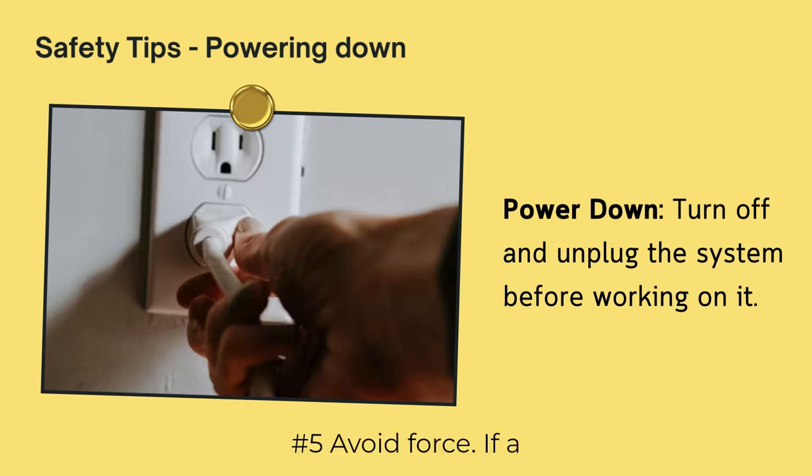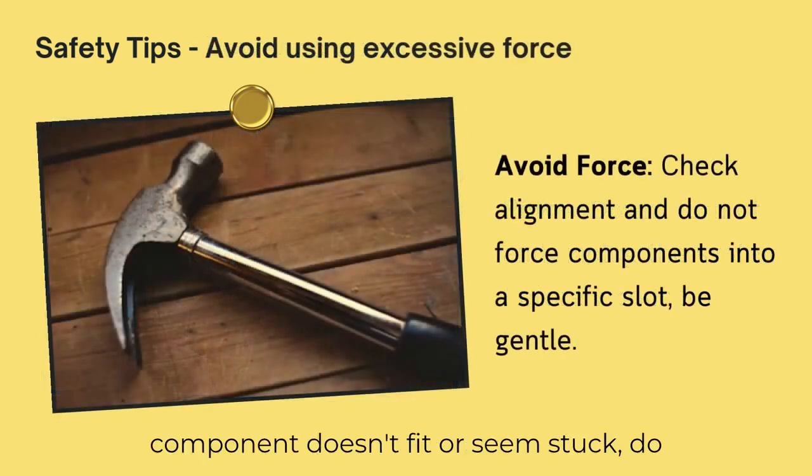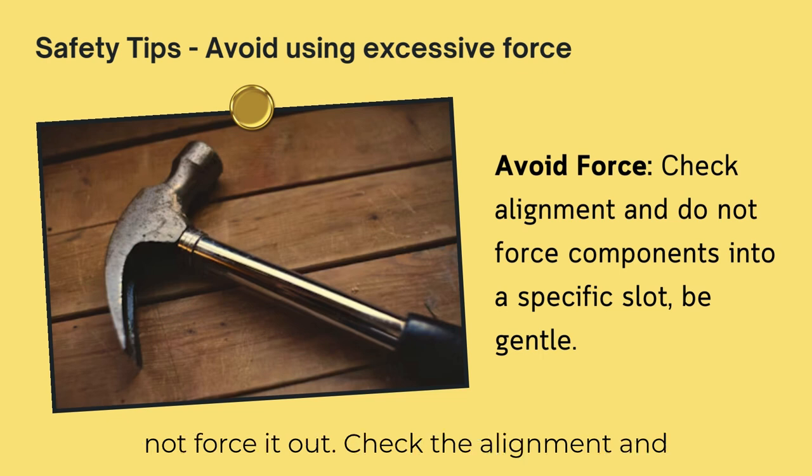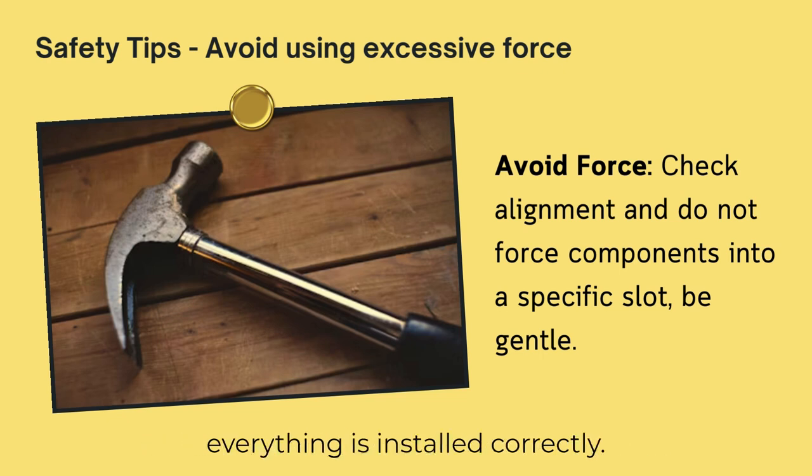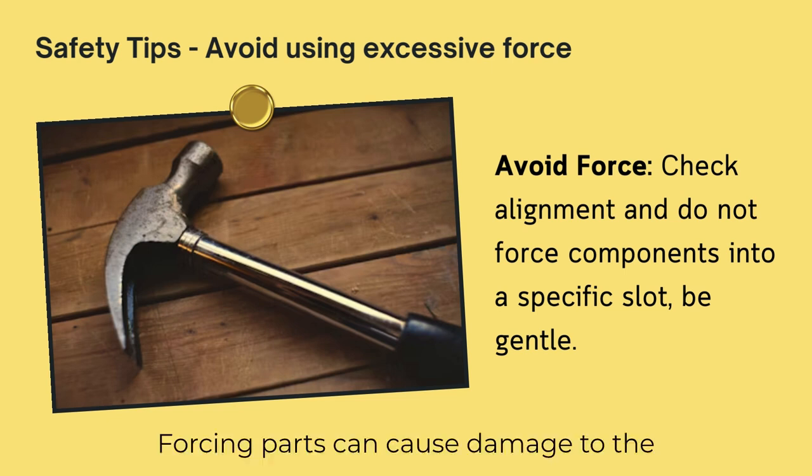Number 5. Avoid force. If a component doesn't fit or seems stuck, do not force it out. Check the alignment and connections carefully to make sure everything is installed correctly. Forcing parts can cause damage to the motherboard or other components.